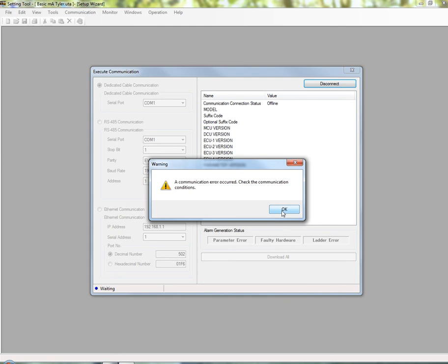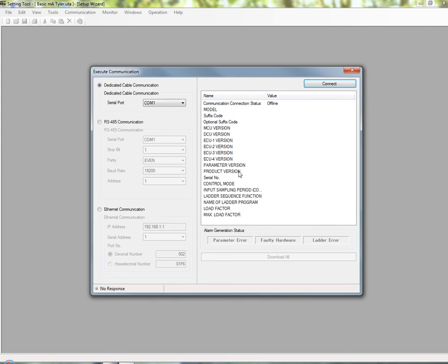And this is a common error, and it usually has something to do with our COM settings here. You'll see that I have a couple of choices, COM 1 or COM 4. So if you find that you get that message, try a different COM port, hit connect, and you'll see now that we're online. It tells us we're talking to a UT55A 040100. This 4 is that 4 that we changed on our very first screen, and it tells us just general information. There's really nothing here to worry about.